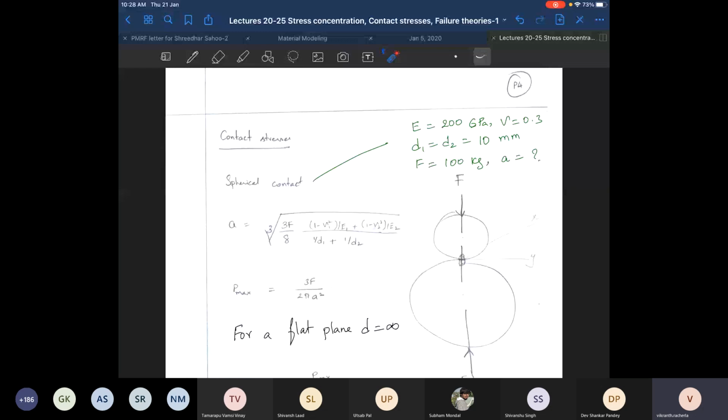Sir, for every step in shafts we need to have two fillets, right? For every edge we need two fillets, for the upper edge and the lower corner. The upper one won't matter. The lower one is more critical because the nominal stress is higher for the lower one. Also, something interesting happens, if you have noticed in the FEM result: if you have something like this and you pull on this, a dead zone gets created. In this region there is no stress in the material. It's called a dead zone. You are unnecessarily wasting the material there if you have a step.